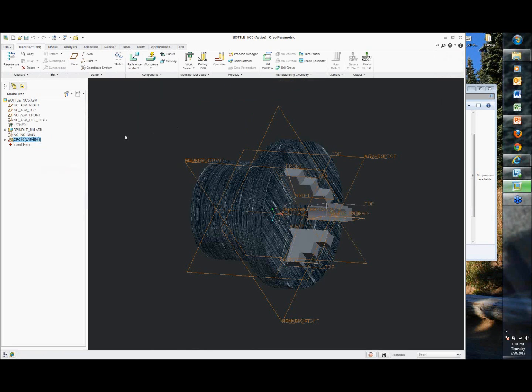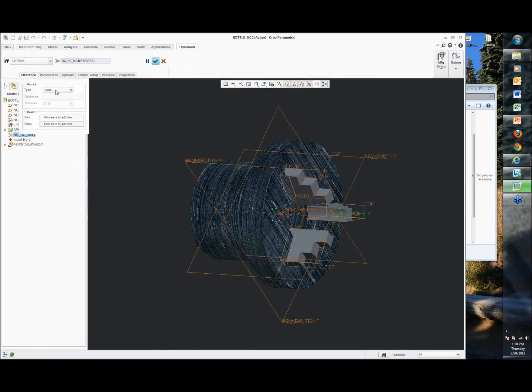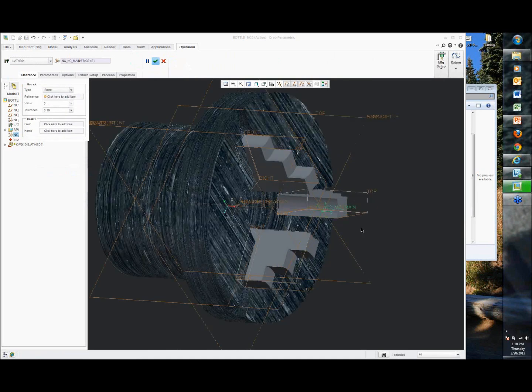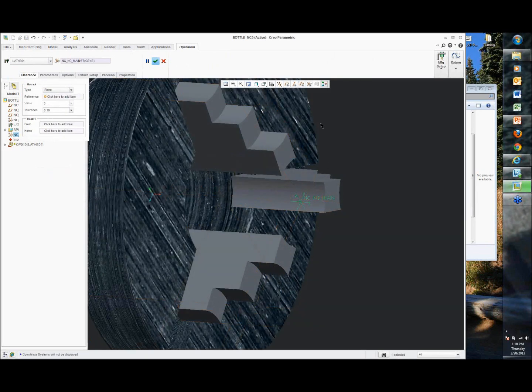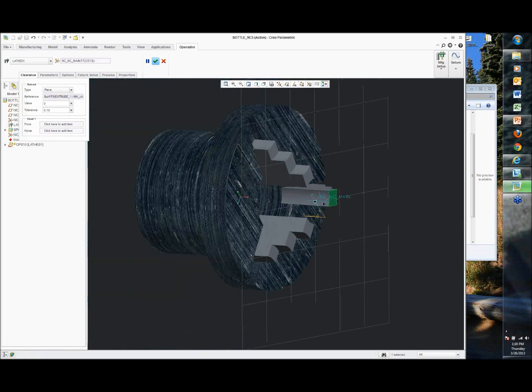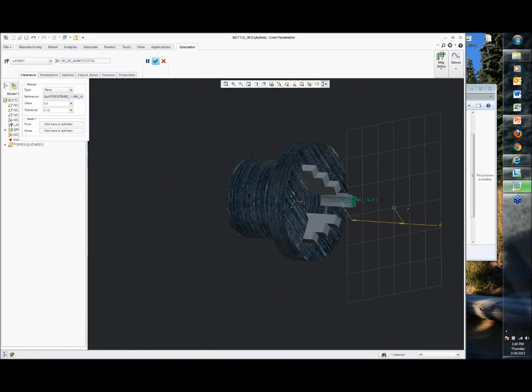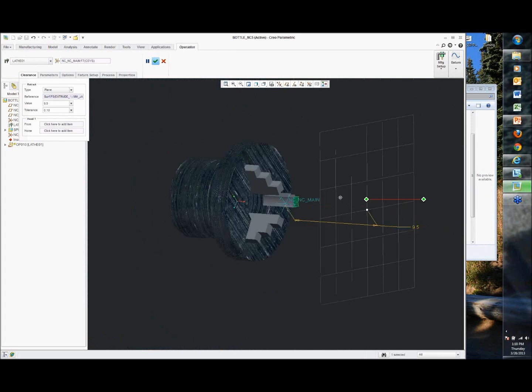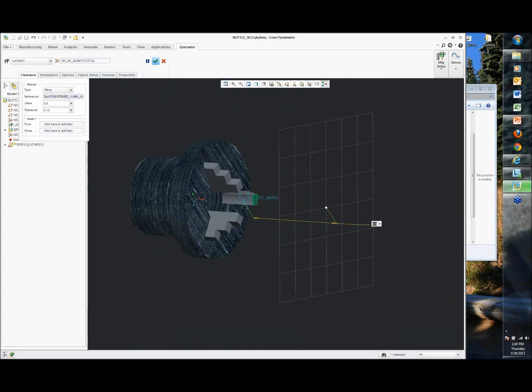I already have a start coordinate system in based on my turret. Let me go back there one second just to make sure I didn't miss nothing. Oh yeah, I can set up my clearance while I'm here, so I can set clearance to a plane, and I can use something like the front jaw there to specifically give myself some clearance. I know that the bottle I'm going to work on is about 7, so I'm going to go to about 8 here, or 9. Let's go to 9. Right? So that's my retract plane basically.